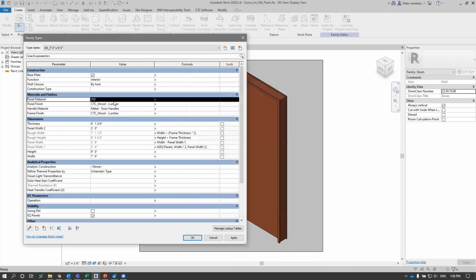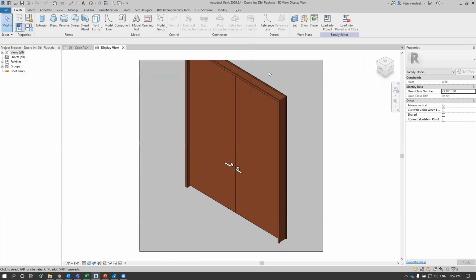So instead, I really have no other option. I can delete this, which would destroy any formula that this is based on. It would destroy anything within the family that is also based on this individual parameter. And then I can put in my brand new one, and hopefully I remember what all the formulas were to be able to put those back. And hopefully I know where all of the different parameters within the actual family are, so I can reassociate all of those. And hopefully I did all of that right. But that's not always the case. We don't always have that option available to us.